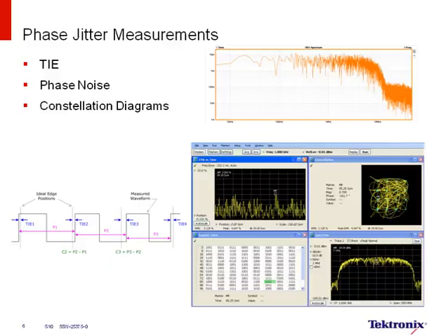The second alternative is to go in there and look at the standards. If you look at the standards document, you will see jitter transfer functions, loop bandwidth functions, PLL order, etc. So you can dial those into the setups because, in general, that is a minimum required spec. The silicon vendor will almost always put in silicon that is better or much better than what you see in the standards requirement. Okay, so that's the best approach to use.